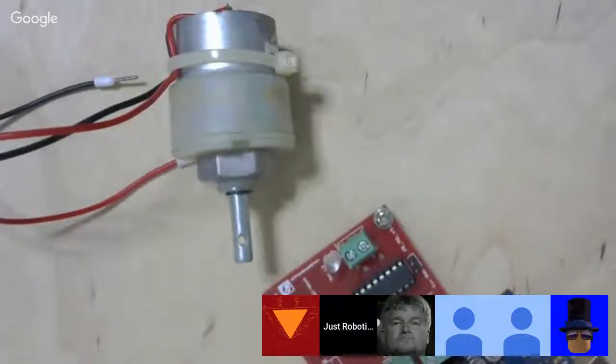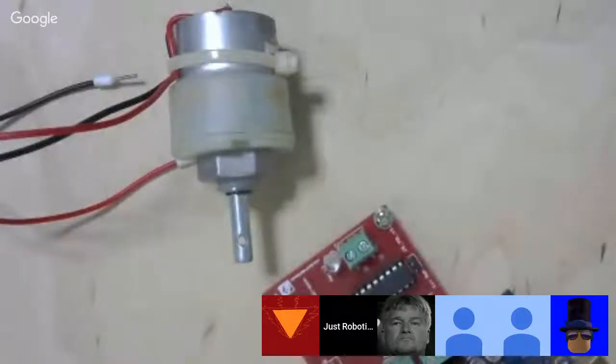Now, why is it required? Not always will I be able to change the battery voltage. I have a constant battery voltage of about 9 volts. Suppose I want a faster robot, I can go with 12 volts, but that will make my robot the faster robot only. I'll never be able to slow it down. Either I have an option to stop it or run it at 150 RPM. So that's what my high or low means when I indicate to the pins I1 and I2. I'm just telling it to run at 150 RPM or slow down to 0.